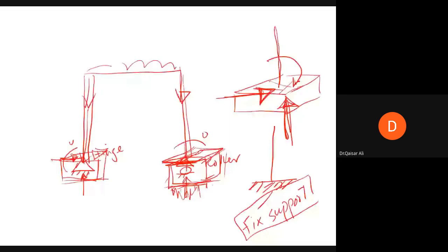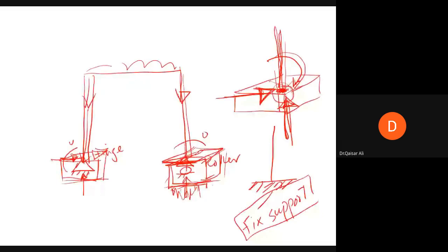to act as a fixed support, the bending moment resistance will be asked of the column and the foundation. The contact point between the column and foundation shall be designed such that enough reinforcement is provided at this column and foundation interface, so that there is bending moment resistance. The column should not fail at the interface of the foundation.